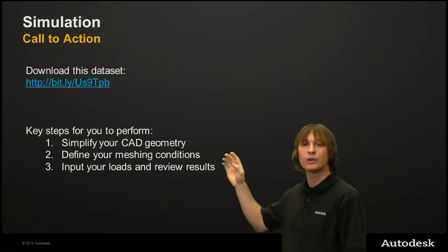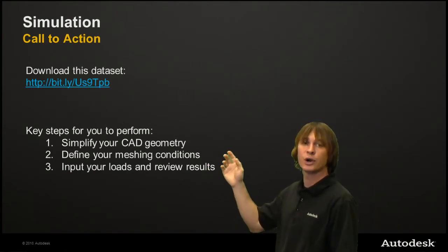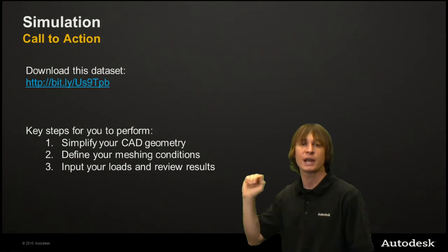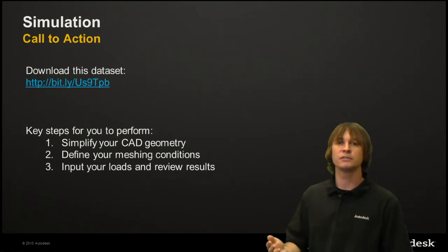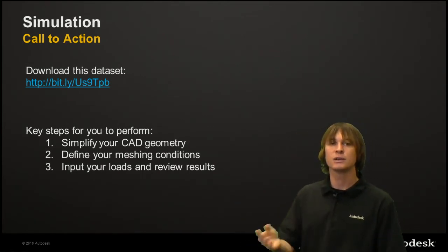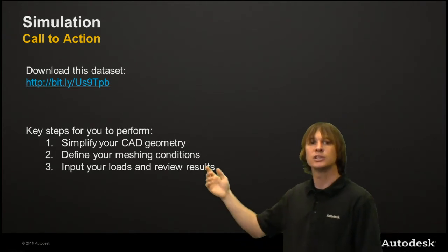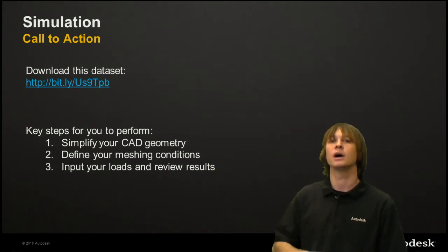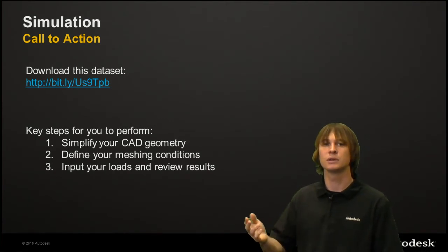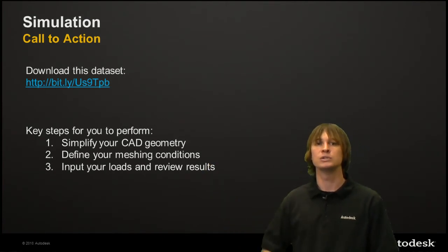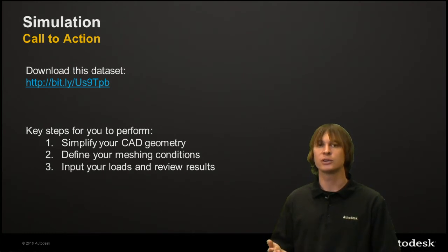The 3 things you're going to have to focus on for this model and for your own would be 1, simplifying your CAD geometry, meaning getting rid of details that you don't need and eliminating parts that aren't necessary for the analysis. 2, define the meshing conditions. A nice mesh is what gives you good results. And 3, input your loads and review these results. An accurate loading condition will result in accurate results for you to look at.